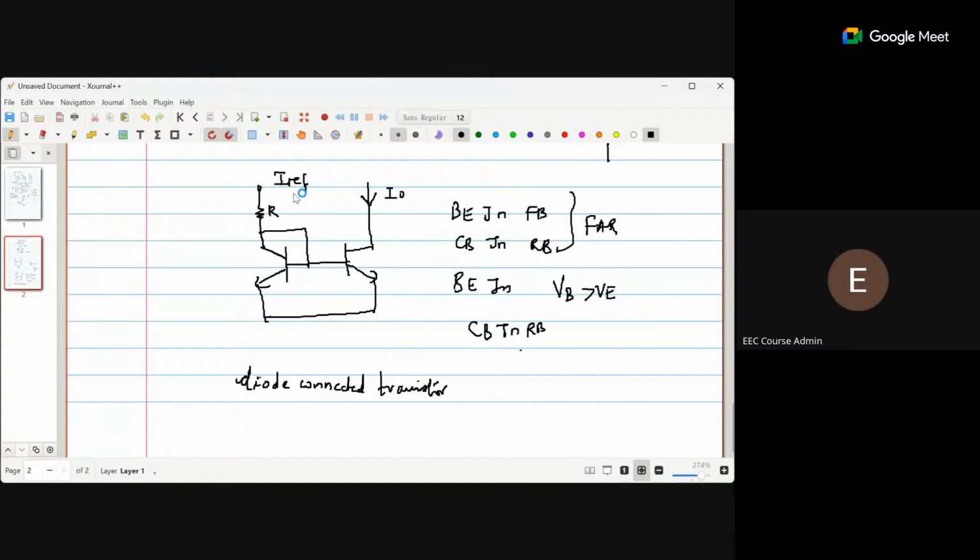So here if you design the circuit, you see that this value of R will determine that mirror current. And another point is these stages here: this is stage 1, stage 2, stage 3, etc. If you have n number of stages, the base current is getting fed to the bases of these mirroring stages.